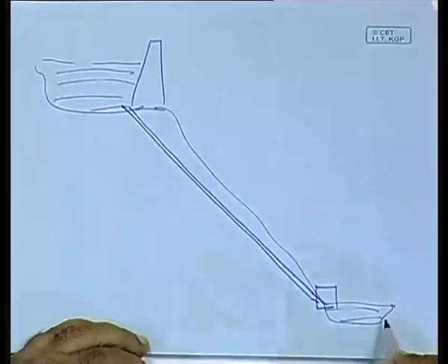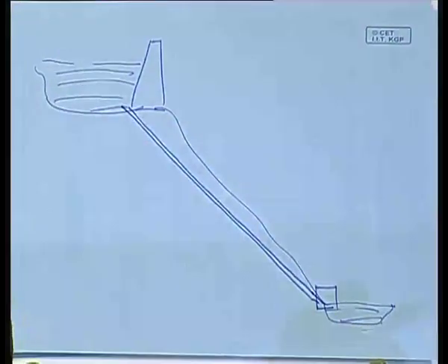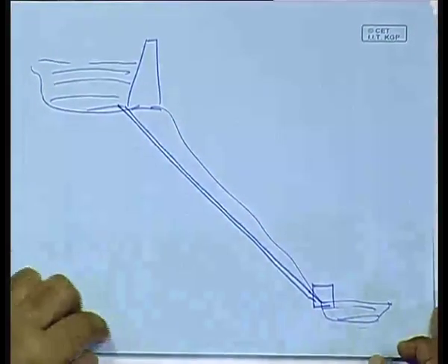Okay. Now you might argue, what is the necessity of the reservoir here? Actually there is no necessity, it's just a stream that goes through. But if there is a reservoir here, you have an additional advantage. What is it? The additional advantage is that, as I have told you, the thermal power plants operate well if they are allowed to operate at the same level of power generation. If you force them to have variation, what are you doing? You are varying the coal input all the time. When the coal input goes down, then obviously the power plant works relatively inefficiently. So keep it at a certain level.